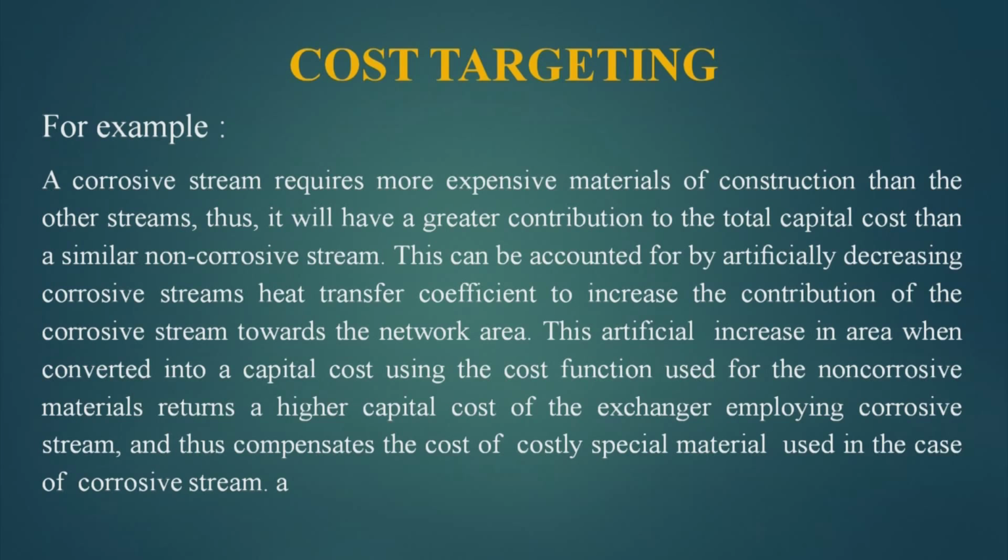This can be accounted for by artificially decreasing the corrosive stream's heat transfer coefficient to increase the contribution of the corrosive stream towards the network area.